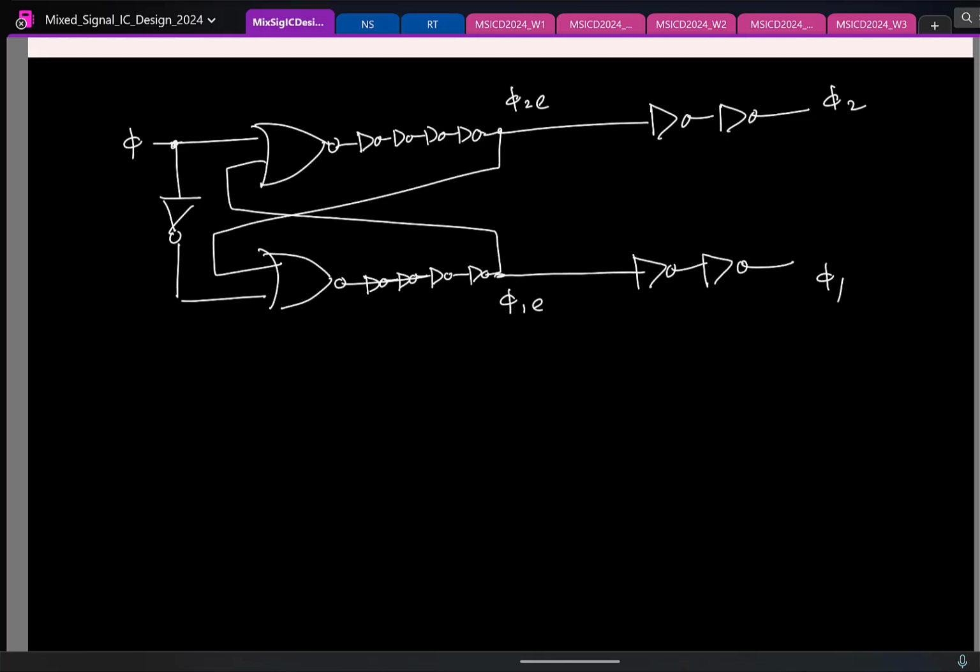So again, to summarize, the sampling network we have right now is like this. The circuit operates in two phases. In clock phase 1 is when we are trying to sample, and for that we are doing bottom plate sampling. So if this is clocked at phi 1, this will be clocked at the early version of phi 1.